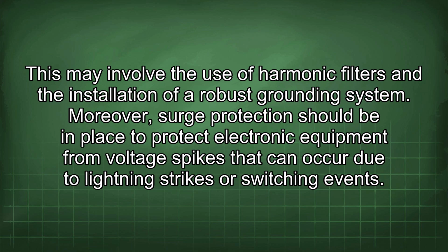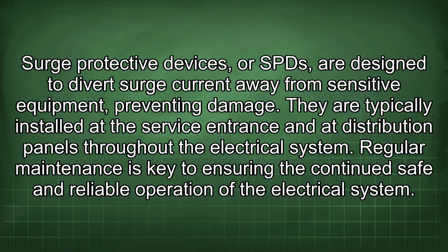Moreover, surge protection should be in place to protect electronic equipment from voltage spikes that can occur due to lightning strikes or switching events. Surge protective devices, or SPDs, are designed to divert surge current away from sensitive equipment, preventing damage. They are typically installed at the service entrance and the distribution panels throughout the electrical system.